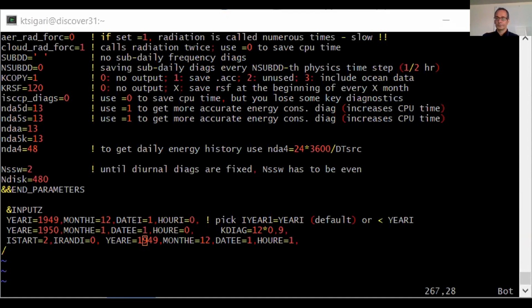The difference between 8 and 9: 9 is usually just to restart exactly the same run, like when you want to continue your run from a restart file. For example, you were doing your run for a very long time, and then it crashed, and you realized that you have to change something very simple to continue. So you change that, and you want to continue that run exactly as it was.